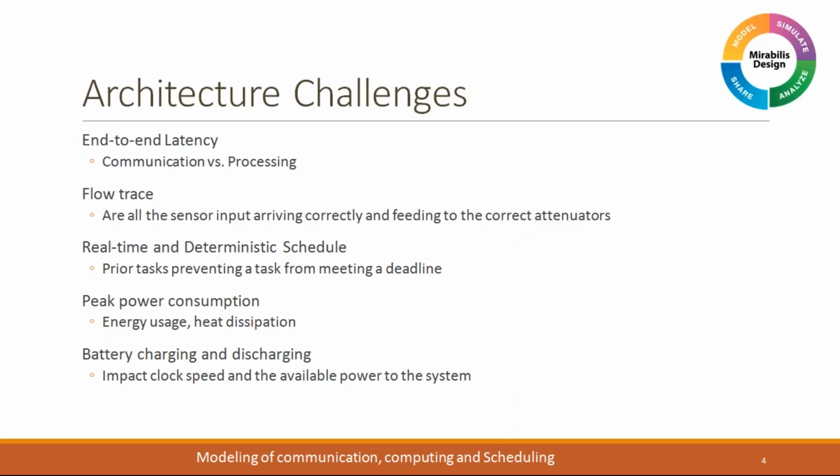One of the crucial characteristics that we see in almost all complex system architectures is limitations of resources. It could be limitations in terms of processing speed or communication bandwidth, or memory access time, or if it is a battery operated system, then power consumption is going to be a crucial factor as well. These challenges directly impact the total system performance, and also cause a lot of interdependencies between the tasks that you are running on the platform.